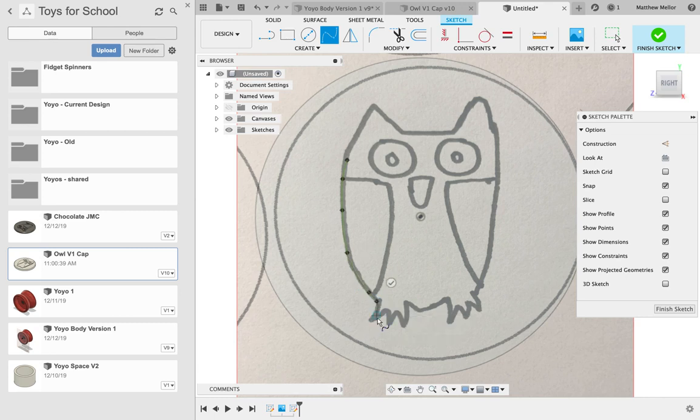All right, so since we're going to be machining these later on, we want to make sure that we don't have any really sharp points or really small cavities. So we're going to edit for that a little bit later. With these feet, you can see that it's coming to a pretty sharp point, but what you'll see as you do this is that